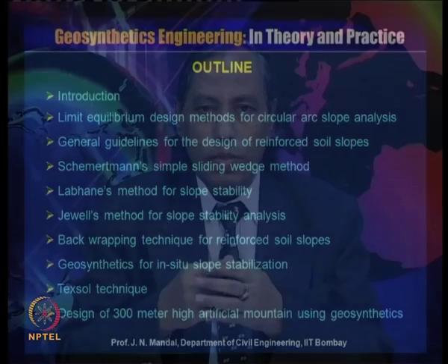So regarding this steep slope stability, the use of geosynthetic material to reinforce the steep slope or the embankment is very common. In general, if the slope angle is less than 70 degrees, we can consider it as a steep slope.